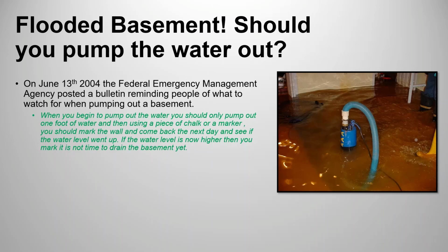First of all, let me tell you that this is the question of lots of people. Because of that, in 2004, the Federal Emergency Management Agency posted a bulletin telling people what to do when their basement is flooded. The bulletin says that you should not pump the water out of your basement immediately. You should wait until the water outside of the basement is going down and the flood is done, and then pump it out. But let's see if we can find out why based on the fluid mechanics principles that we learned today.